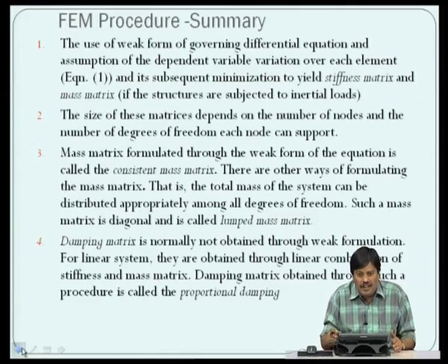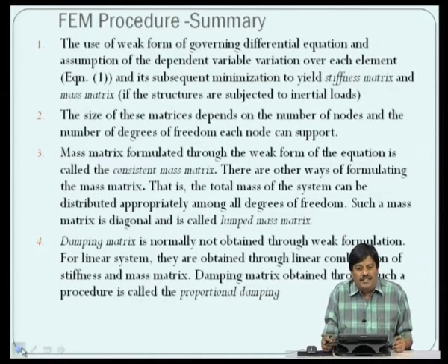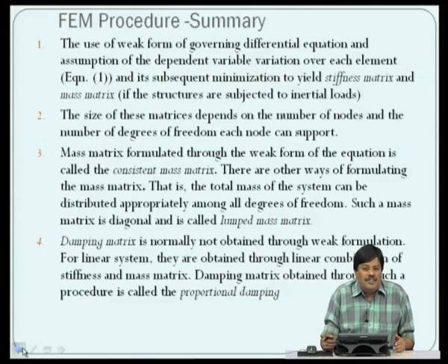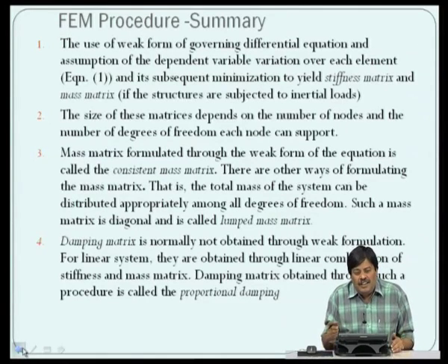through in this course. The damping matrix, another matrix that is coming from the weak form, is many times not used in weak form for many reasons, because damping is a very complex phenomenon which is not well understood even today, but that has to be there. The damping comes because whenever there is a time dependent force, this force will not sustain the same amplitude, it will die down after some time because of various reasons such as the environment, such as the material in which the response is traversing, etc.